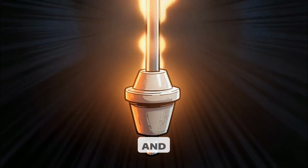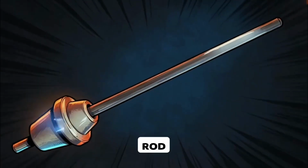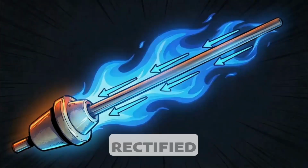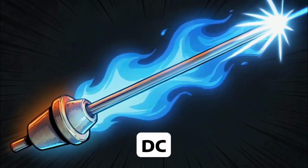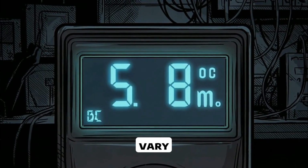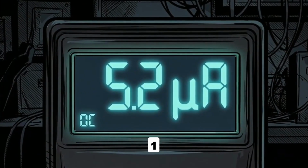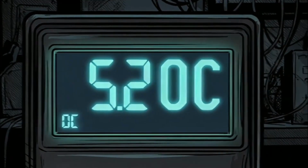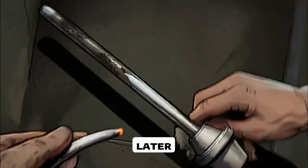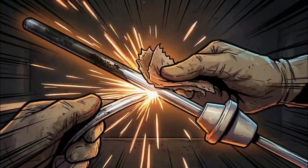Now, flame rods and flame rectification. Modern furnaces often use a flame rod. The control board applies AC voltage and the flame allows rectified current to flow back as a DC microamp signal. Typical flame signal readings vary by manufacturer, often in the microamp range, such as 1 to 10 microamps or more. If the rod is dirty, the burner may light and then shut off seconds later. A dirty flame rod causes many service calls.